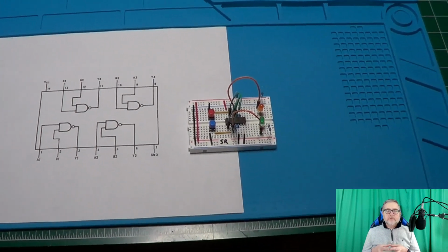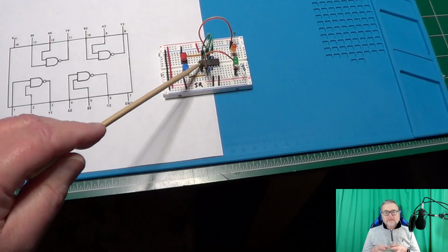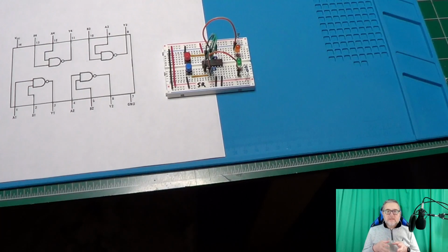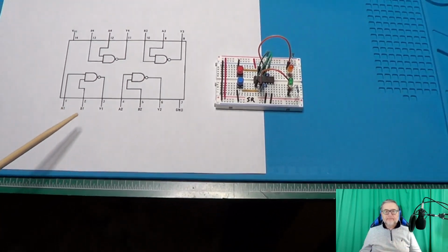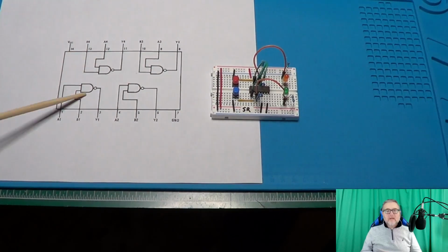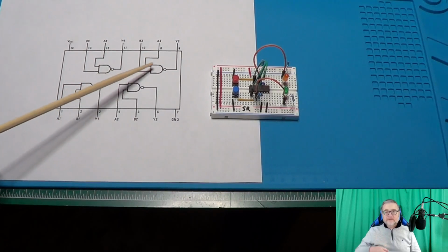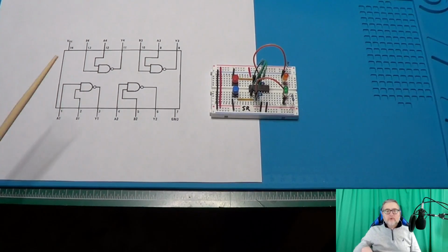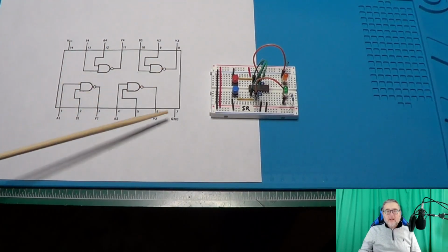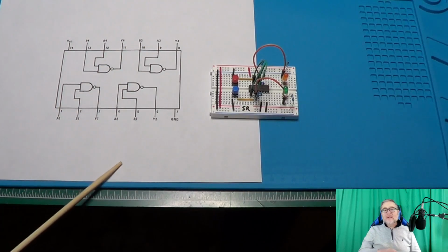This is the circuit mounted on a breadboard. This IC is an SN7400, which contains 4 2-input NAND gates, and this is its internal representation. I assembled the circuit using these 2 gates on the left, leaving alone the 2 gates on the right. In order to avoid interference from the gates on the right, I avoided an unstable state by connecting both of their inputs together and to the ground. This way, the 2 gates will have a stable 1 as their outputs.